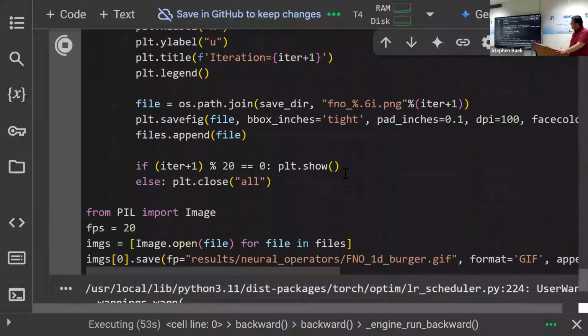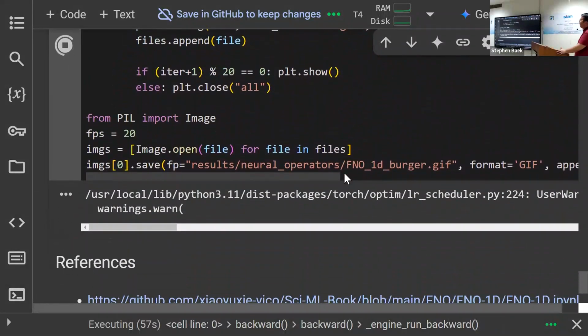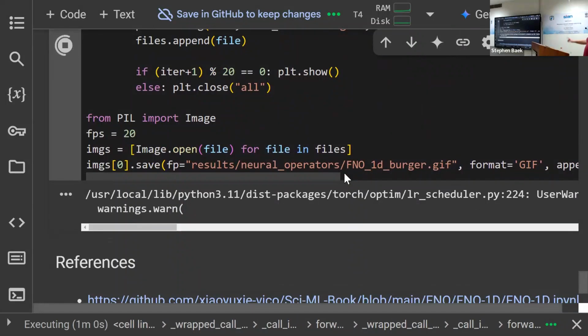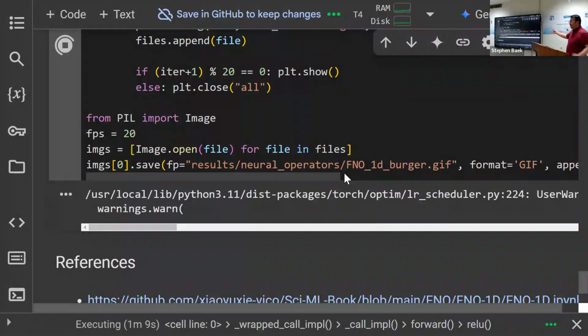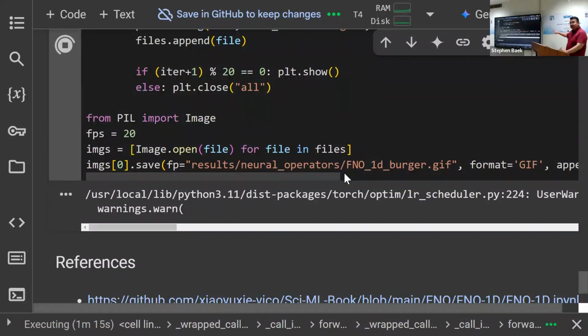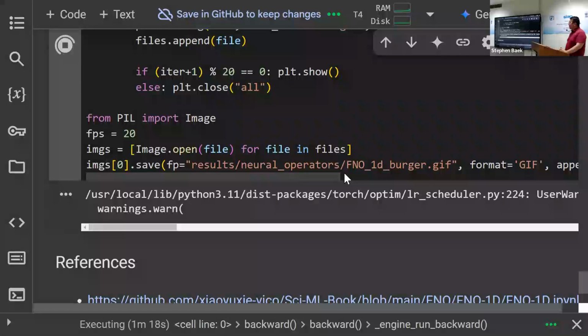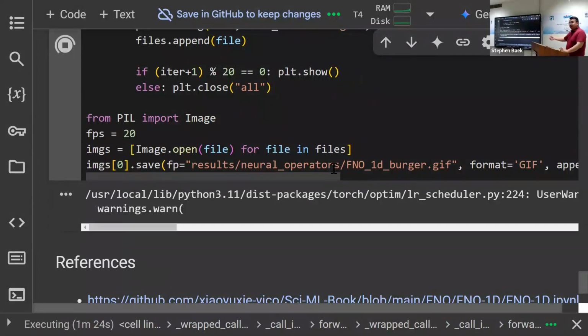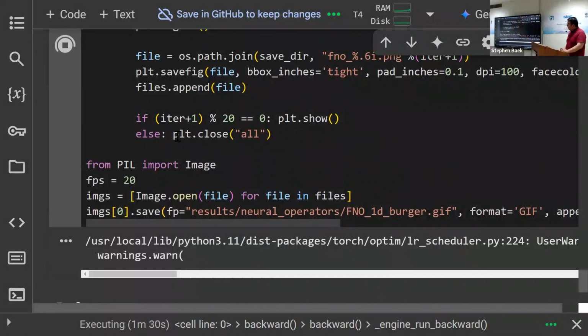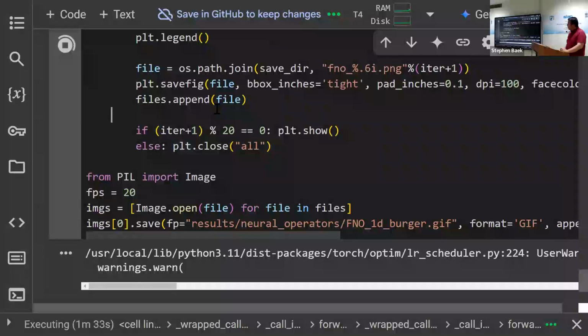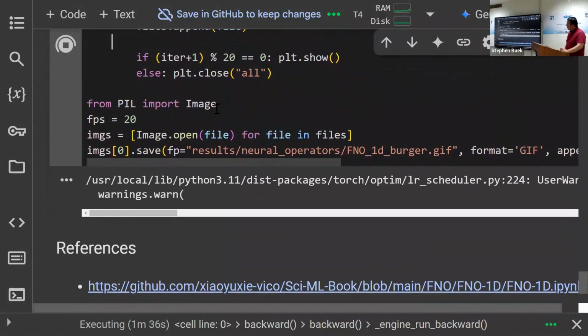And then after the convergence, you'll be able to see how the neural operator performs on the test data set. So, test data set, roughly 15% of the samples we set aside. For those unseen examples, we're basically testing if the neural operator will be able to make an accurate prediction. And for this 1D Burgers scenario, it does a fairly good job. I can show you once the training is done. But that's really what it is.